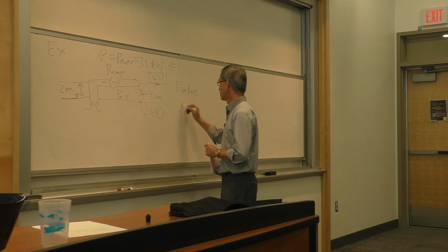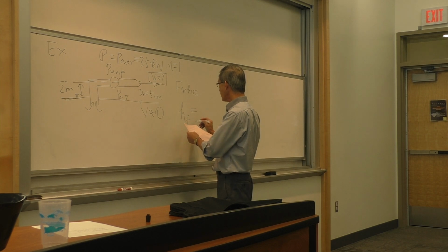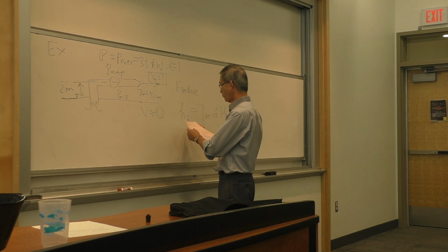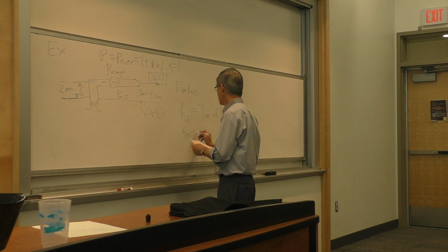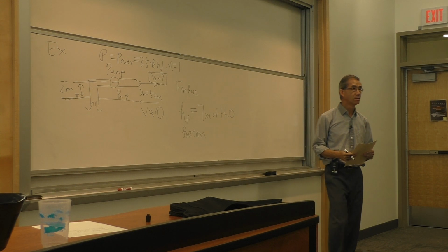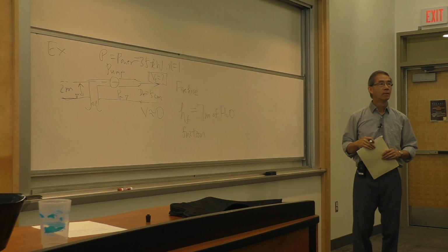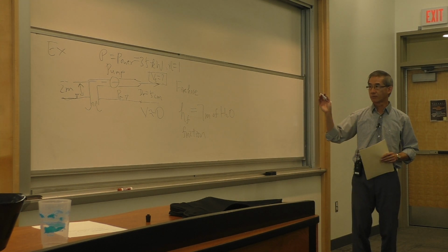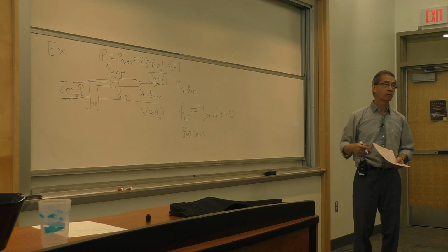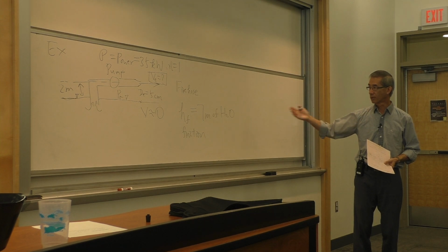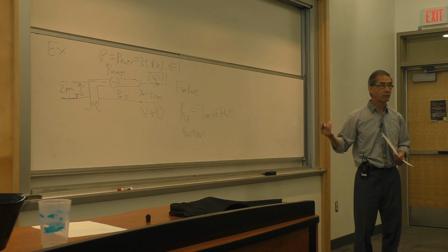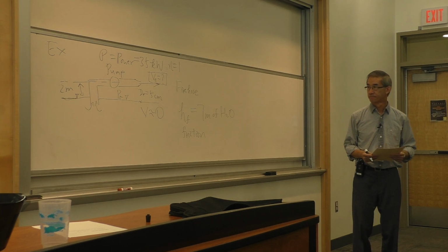Viscosity, very good, which for now, we were told that the friction effect is given in terms of an equivalent height, and we'll deal with that later. This is just the first step. To account for the friction in this pipe, you are not told what the pipe diameter is and how long, but you're given the equivalent frictional loss due to the water, which is equivalent to 7 meters of water. And we'll later on see how that can be used.